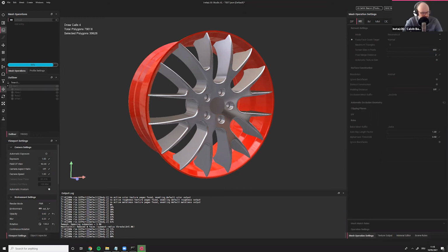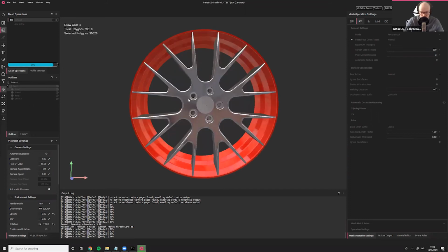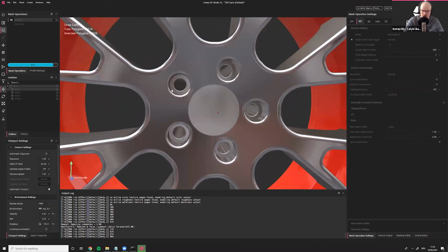Another question is, you spoke briefly about additional functions and you mentioned the possibility of filling holes. How exactly does your software deal with this? Is there some intelligence behind it, like repeating patterns, etc.? So first of all, regarding filling holes, we are currently working on an algorithm that is going to fill holes differently than we're doing it right now. At the moment, we are limited to filling holes that are based on boundaries. Okay, so an actual non-watertight mesh. So for example, here with this rim, this is actually not a hole, even though you would say that this is a hole for these screws.